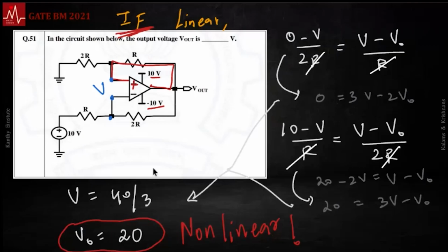So this input will dominate. It will saturate at minus 10, because this is 0, right? It almost behaves like a comparator. What is here is certainly higher voltage, this will dominate and then goes to minus 10.